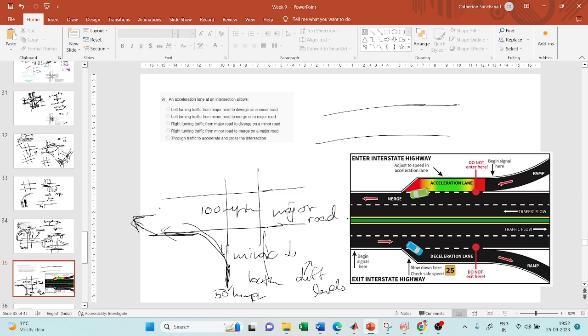If not, it is going to reduce the efficiency of the highway, right? Because all these vehicles will be traveling at a design speed of 100 km/h. Only then can the roadway function efficiently. But if I keep intruding on that roadway with my lower speed vehicles, then its efficiency is going to be reduced. The speed of the vehicles coming behind will be reduced. So when I enter the roadway, my speed has to be on par with the vehicles traveling on the major roadway.